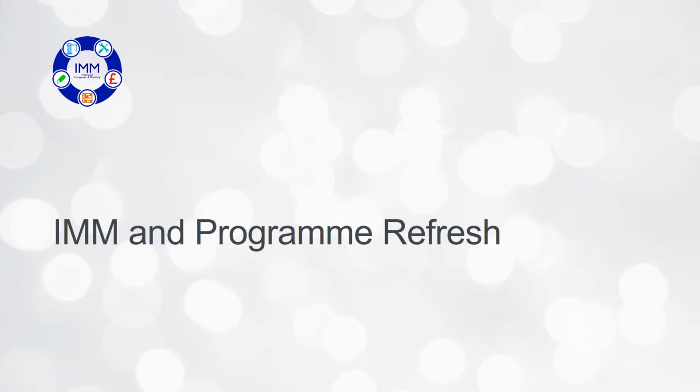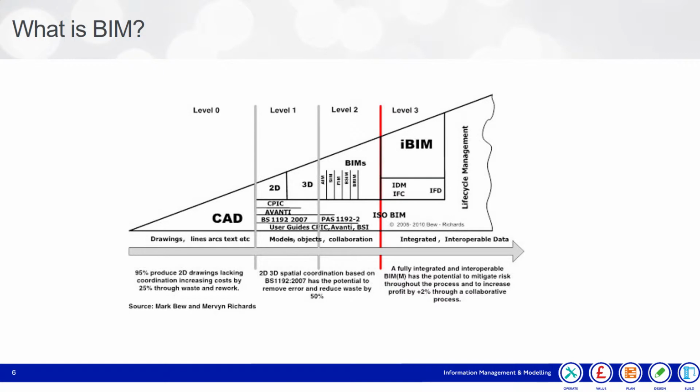What is BIM? The purpose of this diagram is to describe the levels of maturity that precede Level 2, which is TfL's IMM programme aspiration, and to describe the vision of Level 3, which is TfL's ultimate aim. Let's start with Level 0. This is where the majority of surface transport is currently, although we are aware that there are some teams which are working towards Level 2. Information is exchanged by email, 2D CAD drawings exist, and information and data is held in paper format.